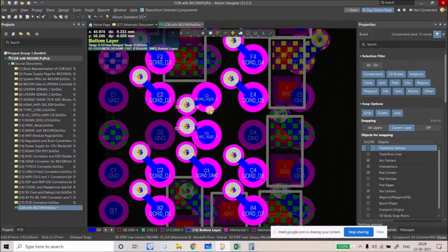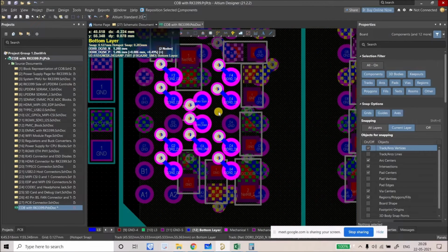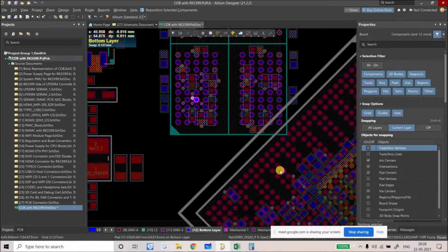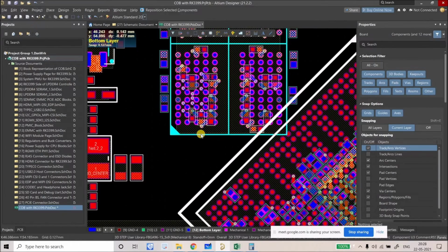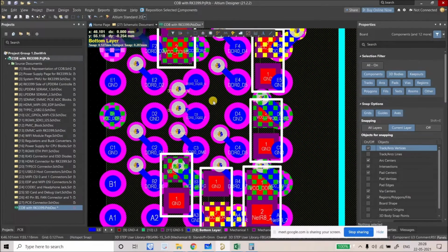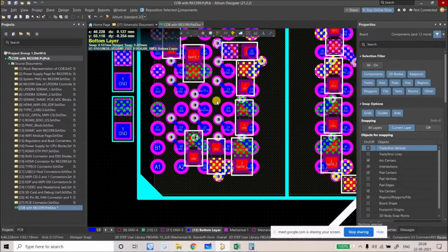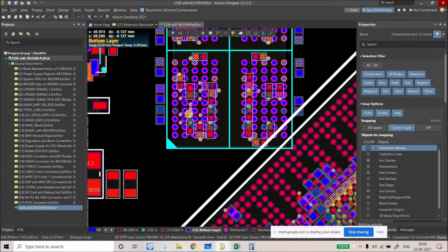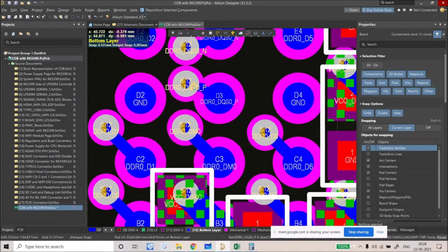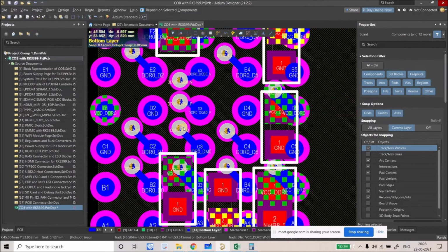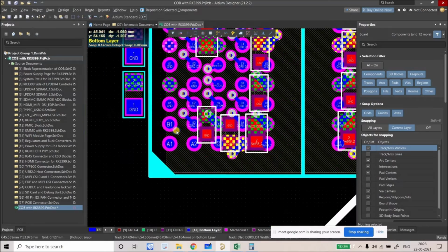So it will be difficult to place tracks and route these differential tracks here, because you have to connect from this end to this end. You're getting it? So you can try that. I never tried placing one here and here, but if it works, I don't think there will be any issue there. So that can also be a solution for this thing.